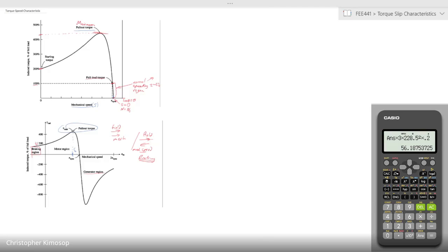Does the 3 take into consideration the 3-phase? Yes, it is 3 because the equivalent circuit, remember, is a per phase circuit. It takes into consideration each phase individually. So the R1, X1, XM, all that stuff is one phase. That is why we use phase voltage, and when we are calculating power, we change it by multiplying by 3. That's why you need to get the total power.